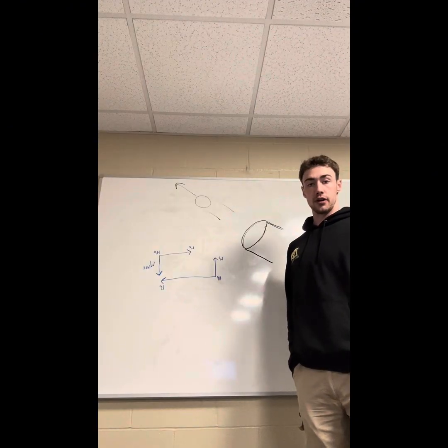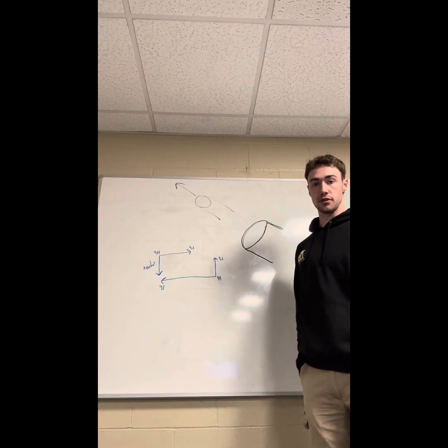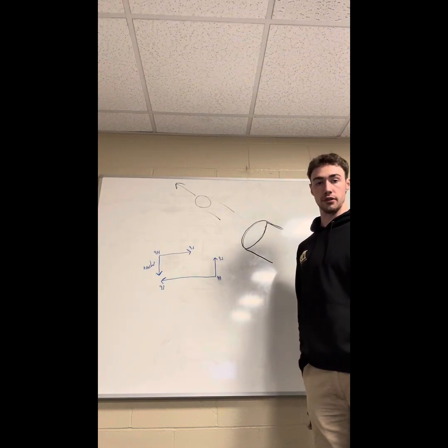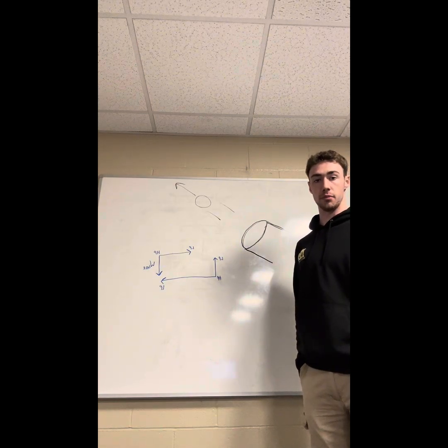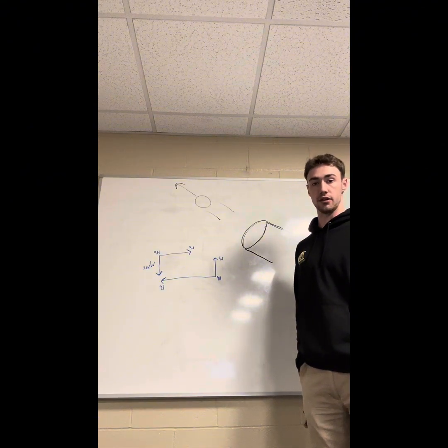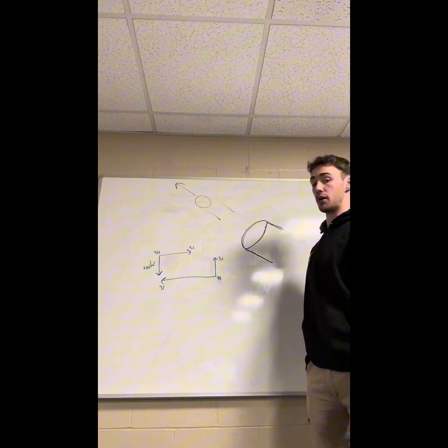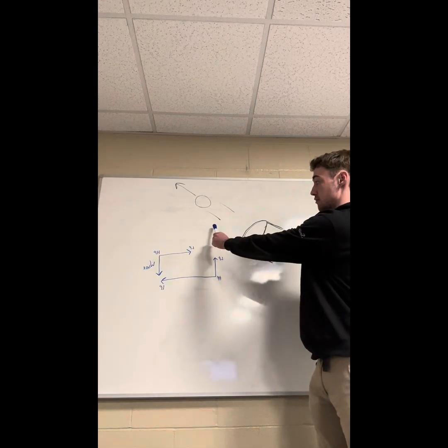Or if you have a strong enough hairdryer, once there's enough of a pressure difference acting horizontally on the ball as you tilt the hairdryer, it can overcome the higher pressure in front of the ball before the weight of the ball overcomes the vertical pressure difference acting on the ball. This results in the ball being ejected out of the end of the airstream.